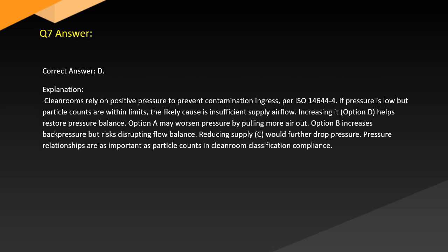Answer. Correct answer: D. Explanation. Cleanrooms rely on positive pressure to prevent contamination ingress per ISO 14644. If pressure is low but particle counts are within limits, the likely cause is insufficient supply airflow. Increasing supply air, option D, helps restore pressure balance.